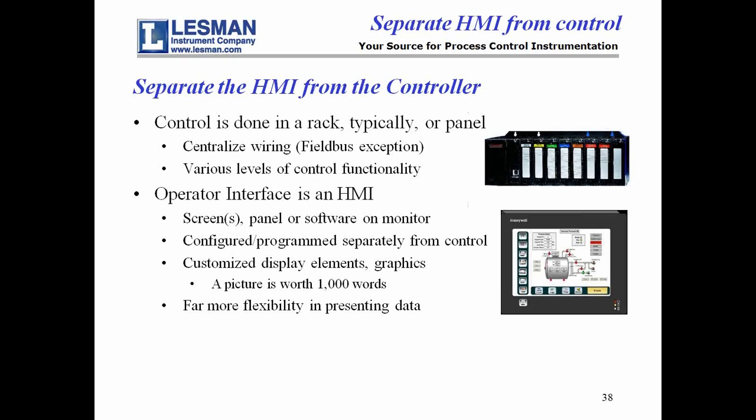They can be networked, which you have to do because now you want to go out to an HMI somewhere and give it the information and let the HMI feed back because, again, the HMI is where people are going to do the supervisory control. They're going to put in their set point. They're going to make their supervisory decisions from the HMI. PLCs are everywhere. It turns out it's not our strength because they're basically discrete control or discrete manufacturing devices.